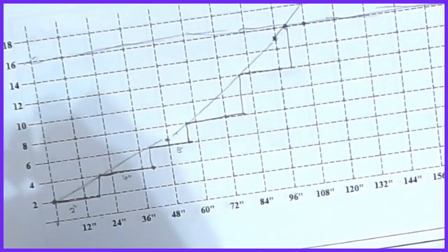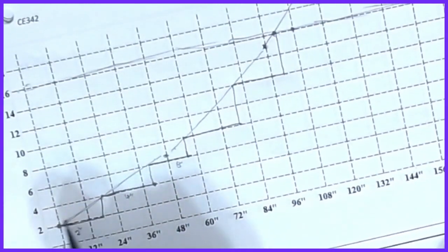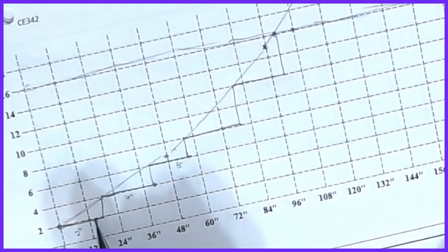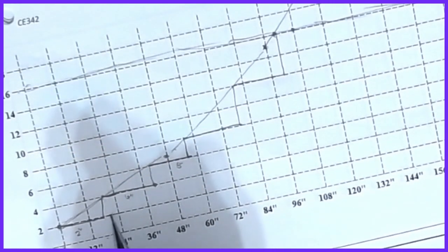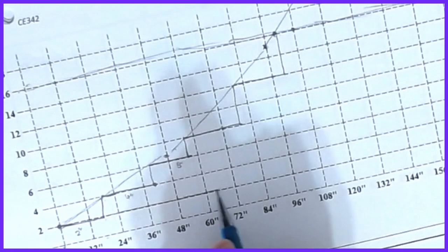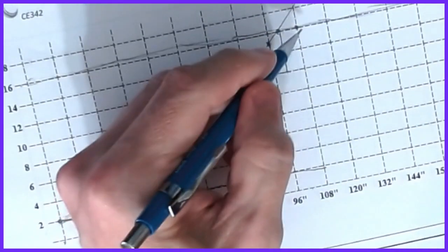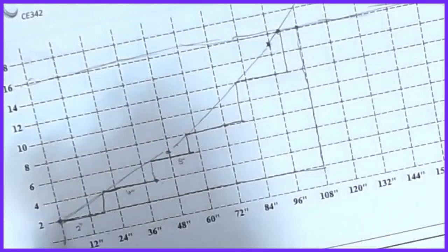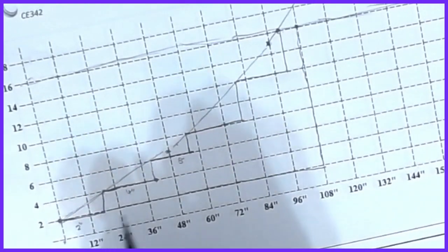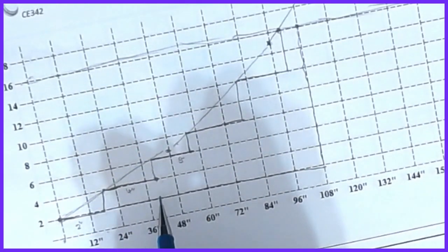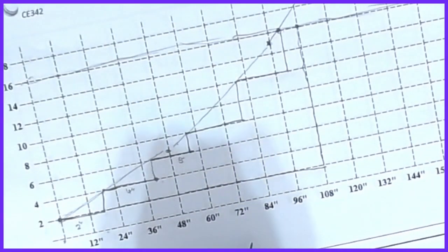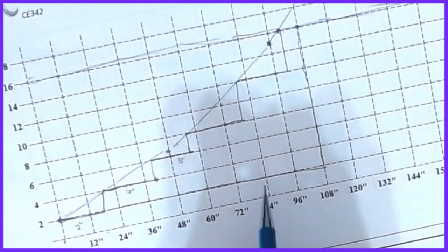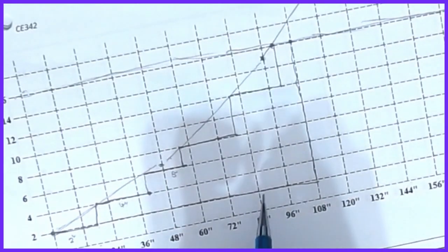Okay, now again, what you don't want to do on this, because recognize that every one of these stirrups is very tightly spaced here. I could take a 2-inch spacing and go all the way over here to S max and come up and do that, and that would be completely valid. But look how much you've overestimated that curve by doing that. You would be doing a whole lot more extra steel install. There'd be a lot more stirrups required, and it becomes a whole lot harder to work on. But that's the basis of the approach that we're going to use for establishing these spacing curves.